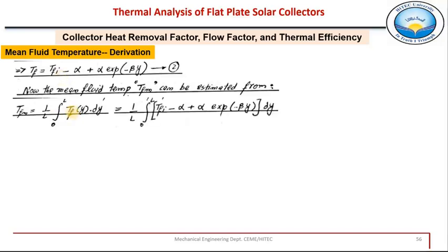So this TF is replaced with this equation. So this whole equation TF at any y is replaced with this one, and actually we need to integrate this equation, because this TF represents fluid temperature at any y, because y is a variable, right? So now we have this form, which is to be integrated.